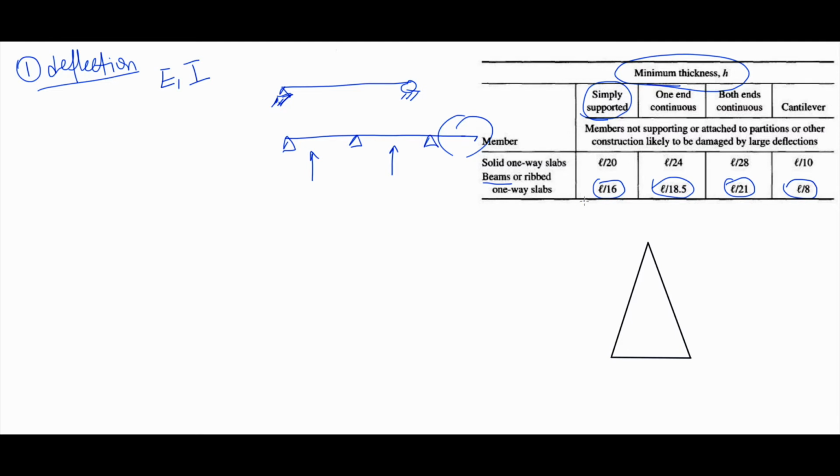Okay, the second thing that ACI specifies, and as I said in the various sources that I've used, is to do an economical beam. Economical beam means D over B is from 1.5 to 2. This is the ratio for normal span, and when I say normal span, it's from 20 feet to 25 feet, or 6 meters to 7.5 meters.